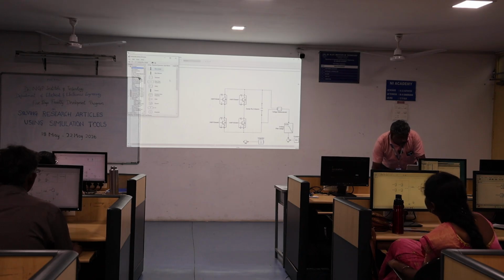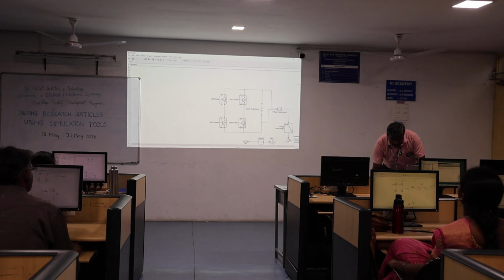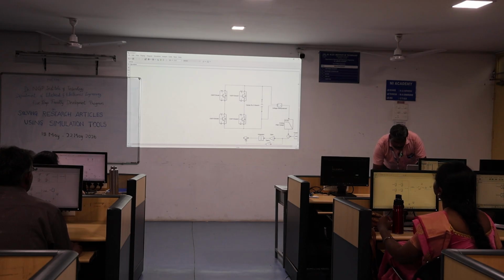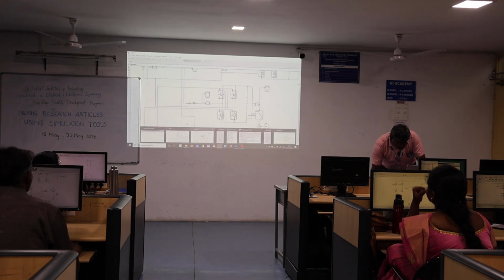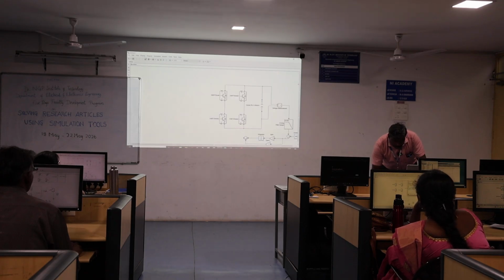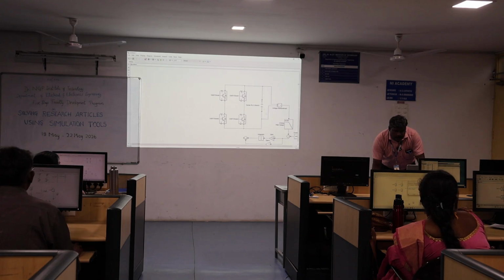Again go to the commonly used blocks, take the gain block, then control R and connect like this. Next take the KP value 1. You can connect directly to the line, or use some block, no issue. So this is the KP value 1, and the integral value 0.5. So now we are going to form the PI controller, to regulate this capacitor voltage.